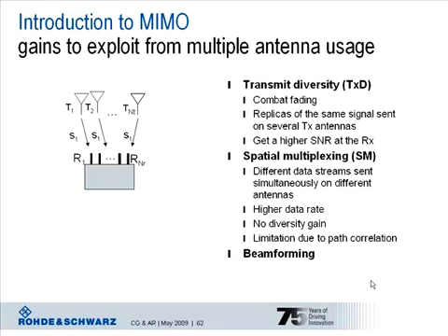However, the data rate cannot be increased because each antenna is actually transmitting the same information stream. You have actually more redundancy available. Note that typically the streams transmitted by each antenna are coded with an additional antenna-specific pattern to further increase the diversity effect. An example would be the space-time or space-frequency coding according to LTE. That is a very commonly used scheme.